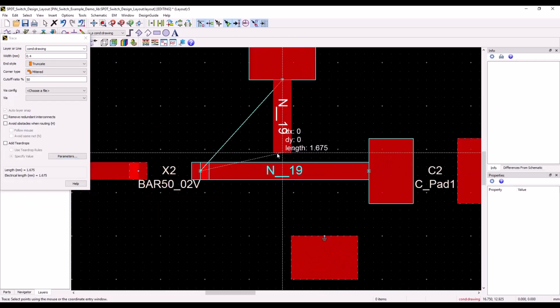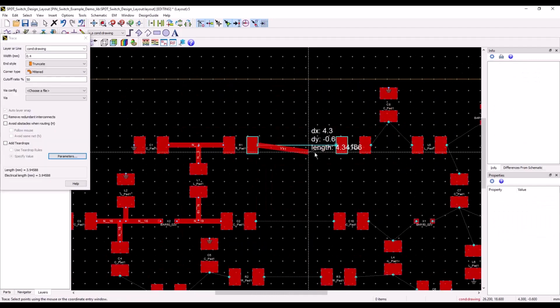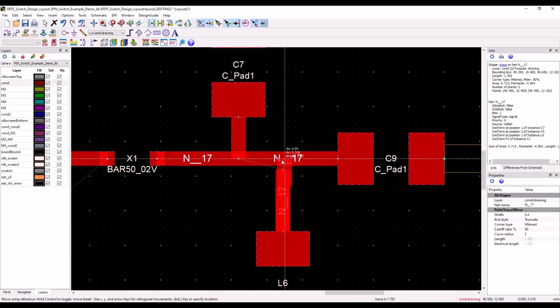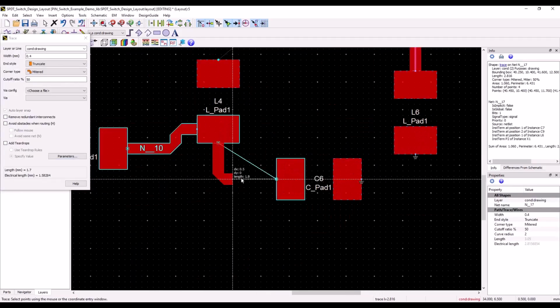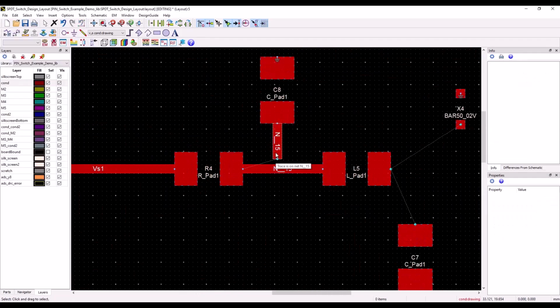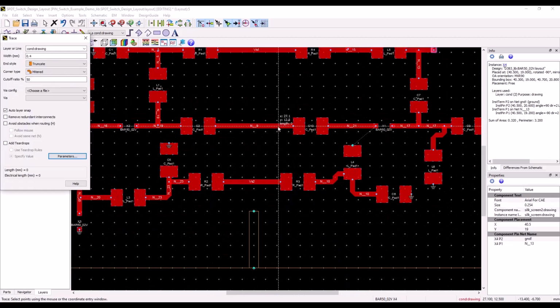And again, if you feel the trace is going slightly oblong, not perfectly perpendicular, you can stop just before the trace and then use the corner point to stretch it in the desired direction, like I'm showing you here. Again, it takes a little bit of practice, but not a whole lot of time, and you would be up and running with the config.